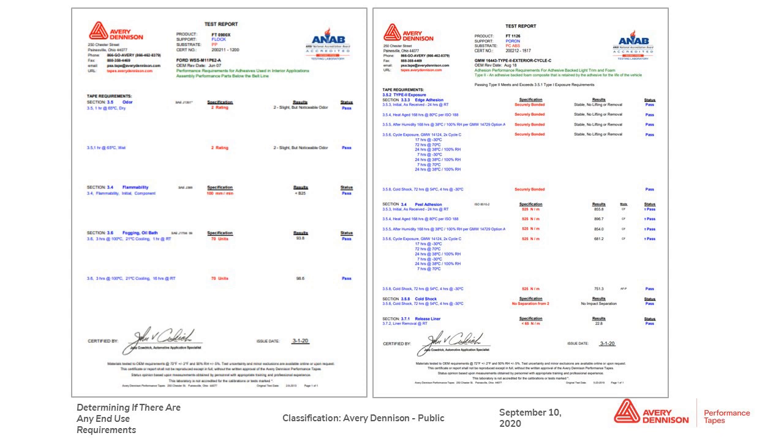Then on the right example here, this particular specification is FT1126 to a Rogers Pour-On foam. The substrate is polycarbonate ABS blend, and the specification is the GMW 16443 Type 2 Exterior Cycle C. We have some more information about that in the revision. And then you can see with this particular specification, there's a lot more requirements than the other one. There are edge adhesion requirements. Edge adhesion is GM's way of saying, does the part remain bonded without peeling upwards or falling off?